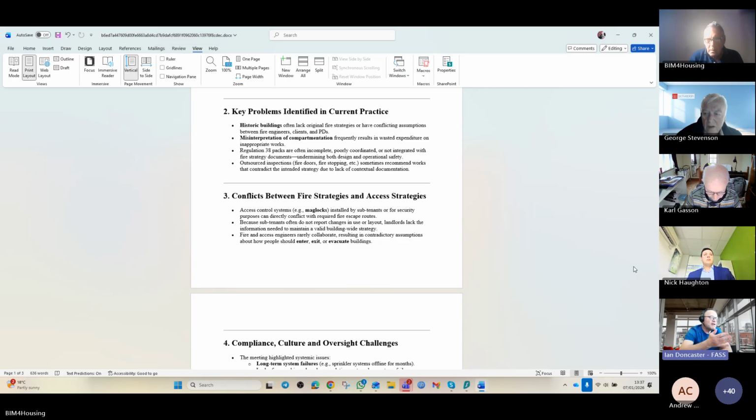So, and there are things that we're not responsible for. We're not responsible maybe for power supplies or whatever. But if someone hasn't shown us that they're there, we can't say our system does what it's supposed to do. And if there is a case where that's not possible, then we would always caveat that on any commissioning certificate, saying it should be checked by a competent person or authorised person or whatever, just to say that the thing actually does work end to end.